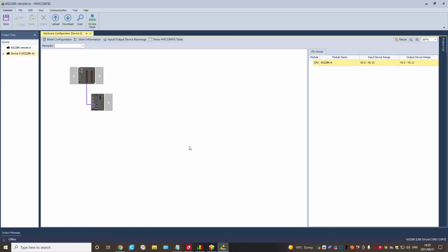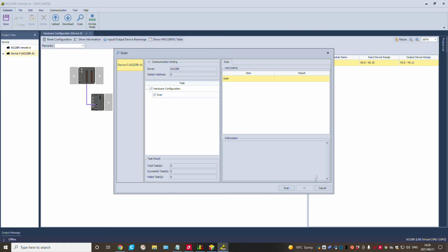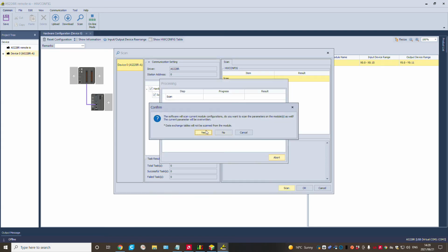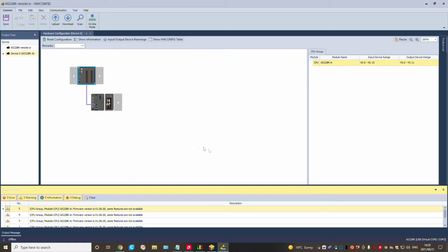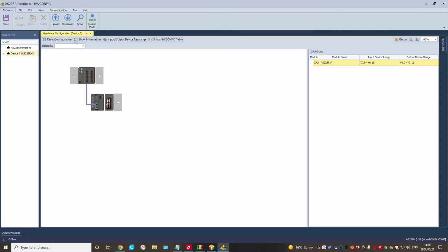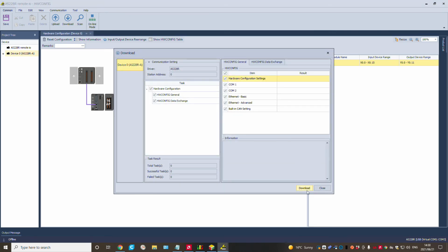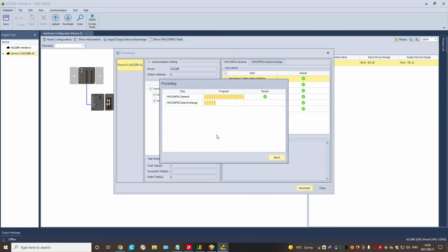After the power cycle, we can give the PLC and RTU module a few seconds to boot correctly. Then we can do a system scan to detect all your installed hardware. If your hardware, connections and configuration were done correctly, you should see your RTU module and your installed I/O modules after the scan is finished. When you see your modules displayed correctly, you can download the configurations to your CPU.